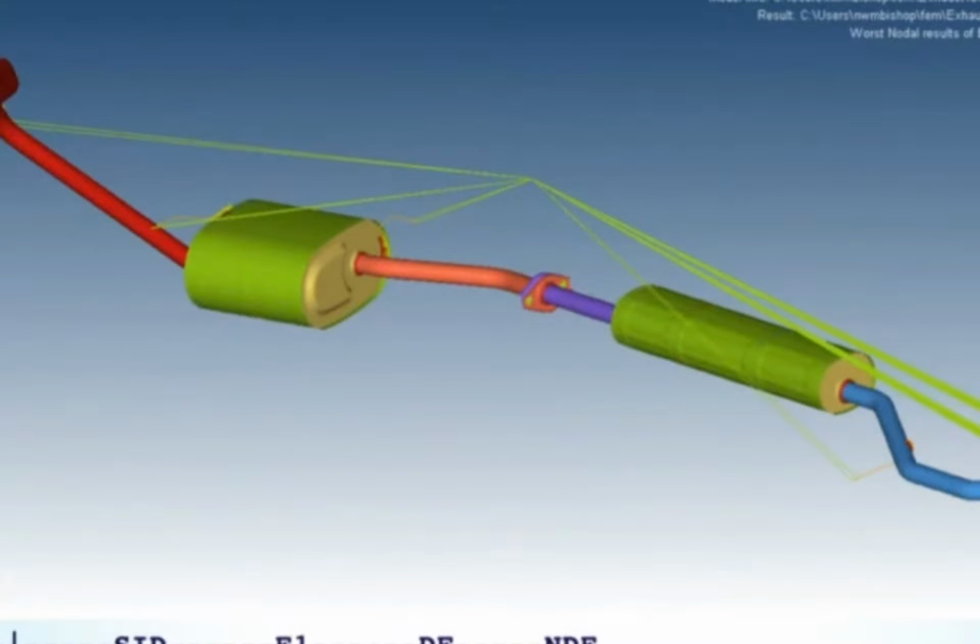So let's now think about the model itself that I'm going to look at. I've taken an exhaust. This particular model is loaded in 3 directions simultaneously, X, Y, and Z, but the whole thing's loaded in those 3 directions simultaneously. So you can see there are some rigid connections to various points, various fixing points on the exhaust. The Nastran job has been set up using solution 111, and the key input to the Nastran run is